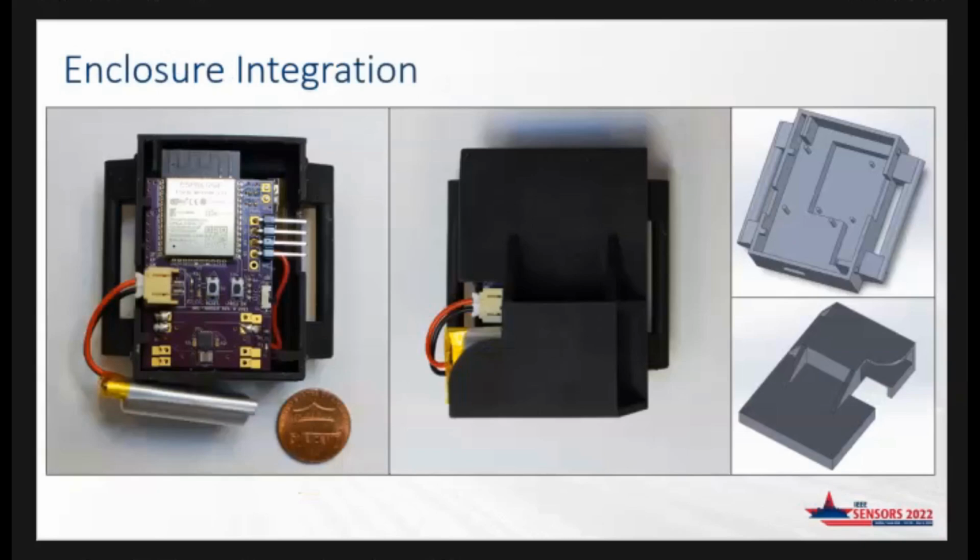One important aspect of being able to do this IMU monitoring is being able to restrain the IMU sensor inside of the enclosure where it's mounted on the body, because any spurious movement of the IMU is going to cause noise in your signal, obviously. So to minimize that error, we designed an enclosure that's specifically aimed at constraining the IMU portion of the device and keep it moving in complete accord with the enclosure itself on the body. So it's not able to shuffle around inside of this at all.